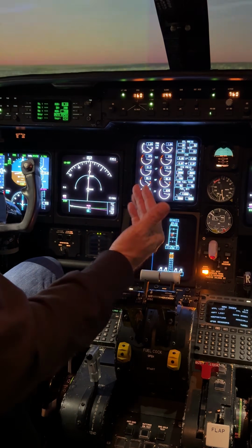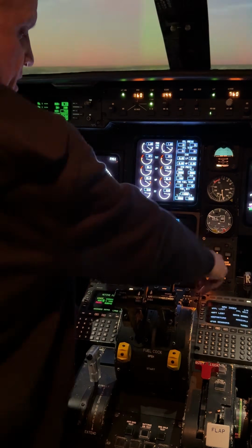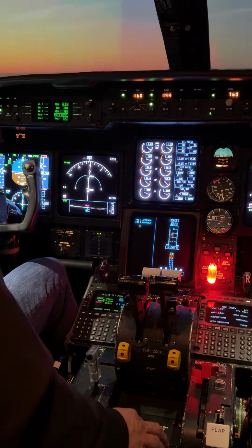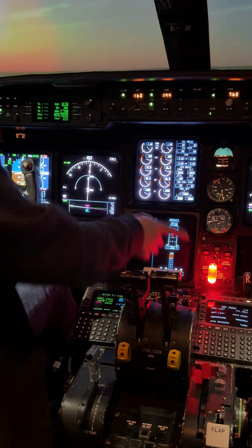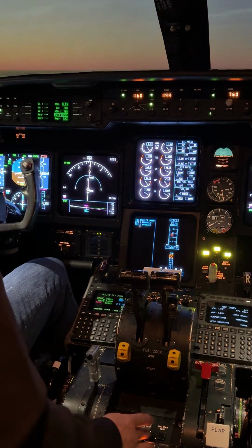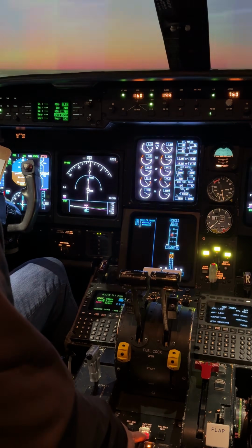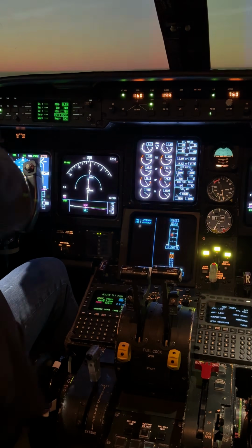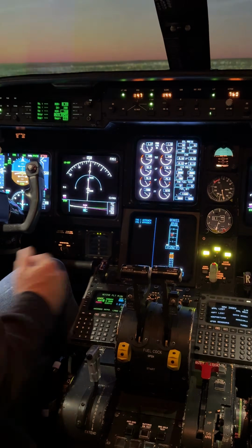So, fully configured before the final approach fix, gear down before landing checklist coming up. I'm a little late on that, just bear with me. Red light means we're in transit. Got the 3 green lights, nutcracker. Yes, 2 lights before we arm the ground spoilers, which we did. Full flap down, warning inhibit is on. Feet off the floor, and you follow the proper checklist.